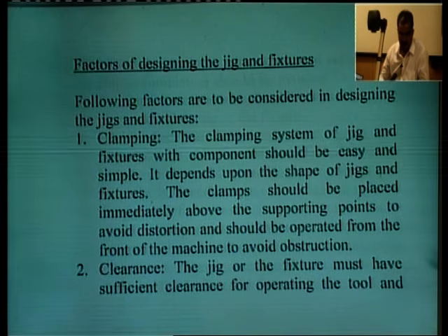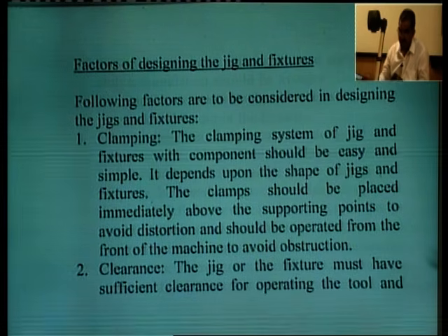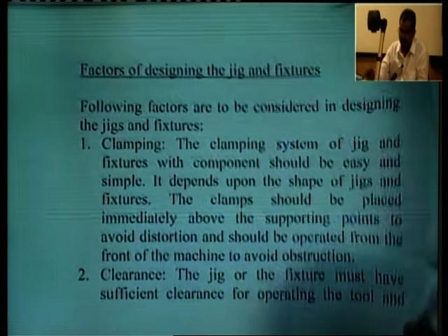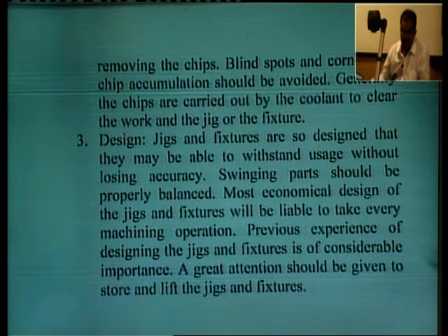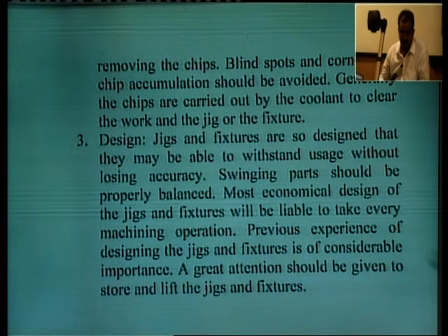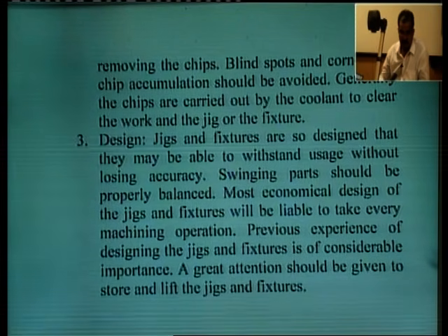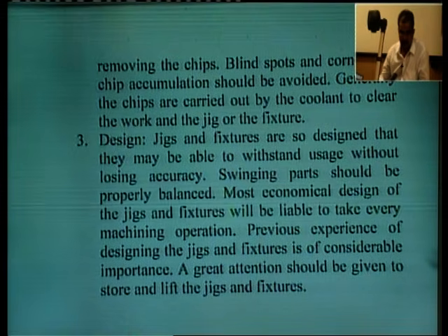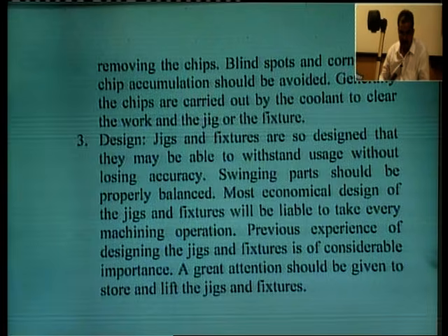And then clearance. The jig or fixture must have sufficient clearance for operating the tool and removing the chips. Blind spots and corners for chip accumulation should be avoided. Generally, the chips are carried out by the coolant to clear the work and the jig or fixture.